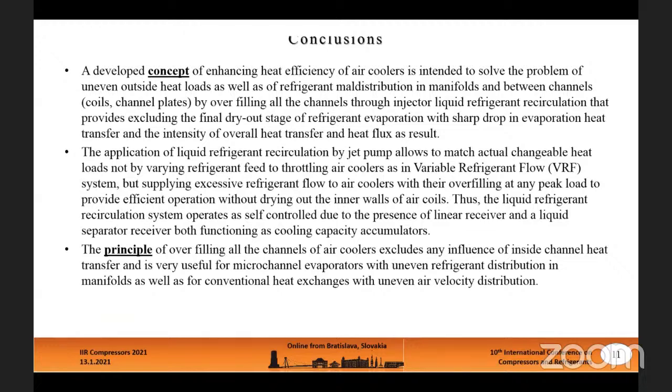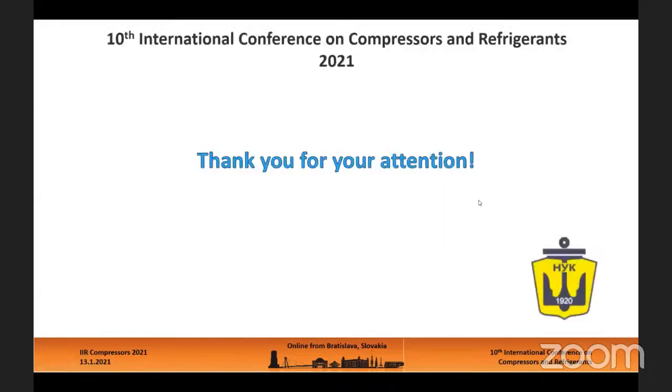accumulators. The principle of overfilling all the channels of air coolers excludes any influence of inside channels heat transfer and is very useful for microchannel evaporators with uneven refrigerant distribution in manifolds as well as for conventional heat exchangers with uneven air velocity distribution. Thank you for your attention.